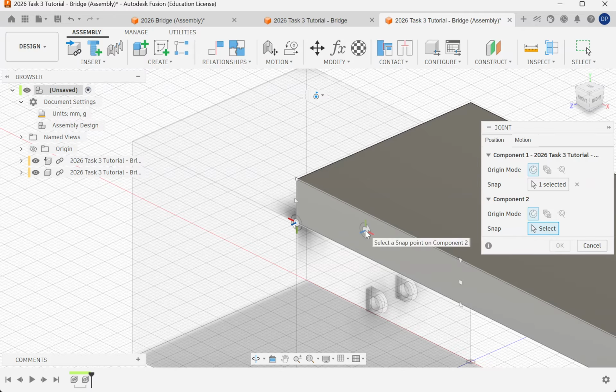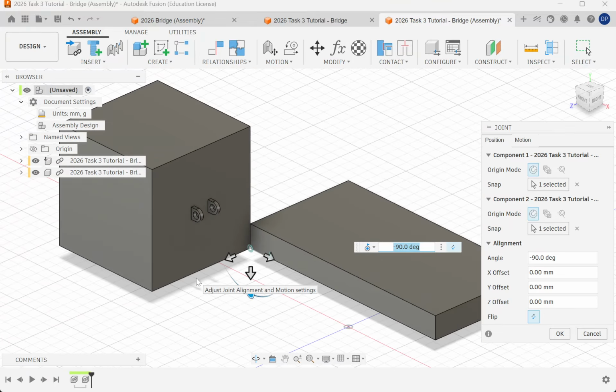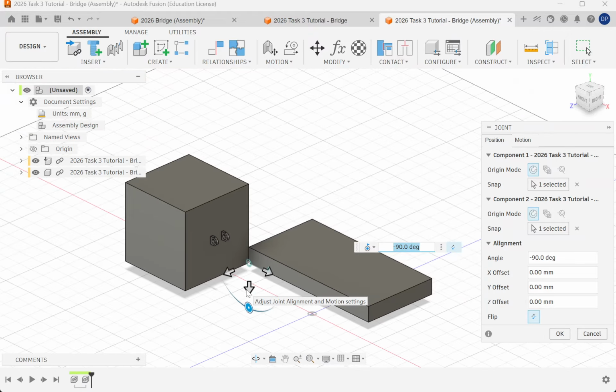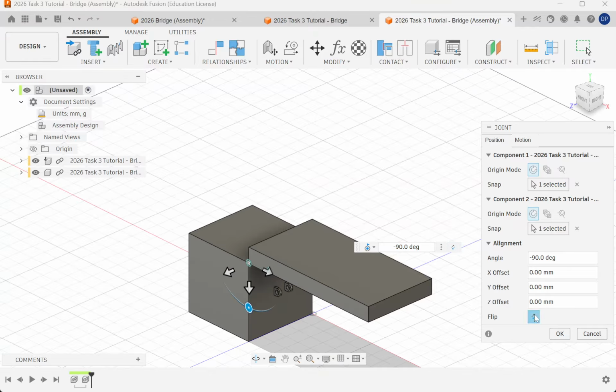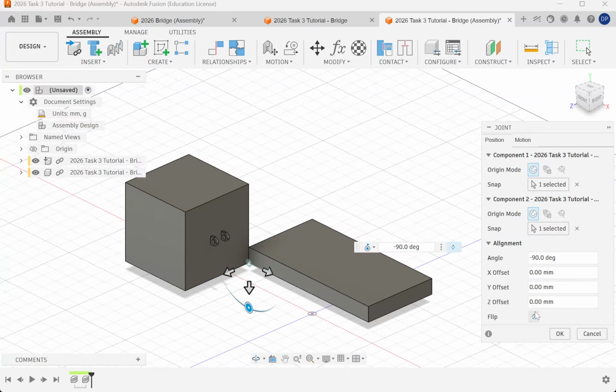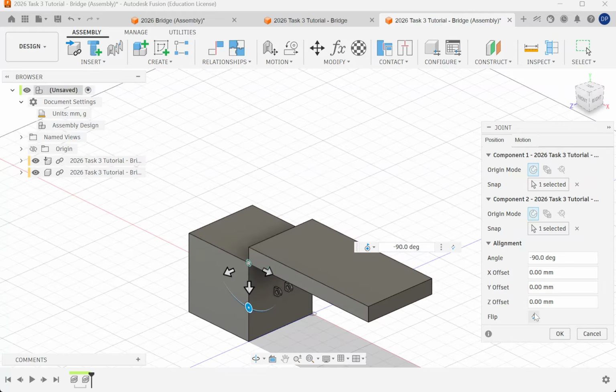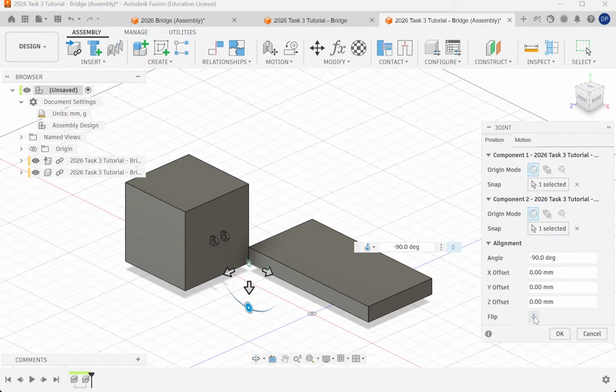I'm going to hover my mouse over here, hold down the control button, bring my mouse to the corner here, and watch what happens as soon as I press this. The screen's going to move. Oh, that's not very nice, is it? We can fix it. We press this flip button to rotate it because we saw that axis coming out to the X. It tries to align those axes mathematically, and so sometimes that can do a 180 flip. So you press this flip button.